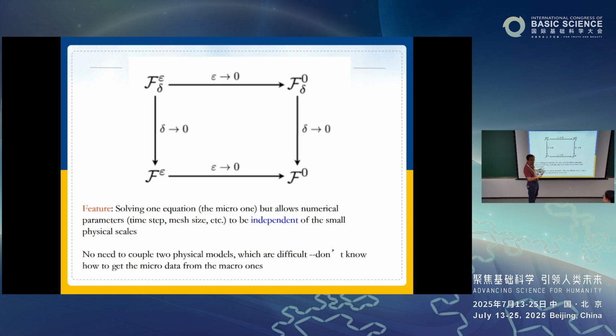Okay, that's numerical convergence. However, if you do a truncation error analysis, this epsilon usually appears as 1 over epsilon. So you find the truncation error will be divided by epsilon. Which means that for consistency, your delta has to be smaller than epsilon. Which means you have to resolve the small scale. If you compute some physical problem with a small scale, your mesh size has to be small enough to resolve the small scale.